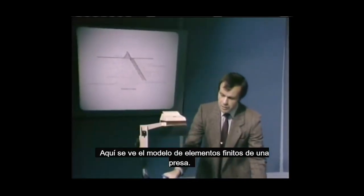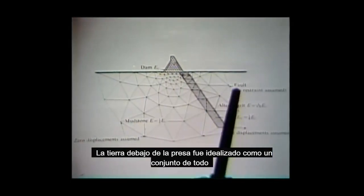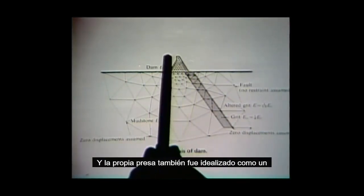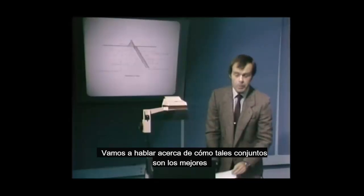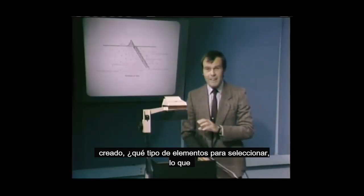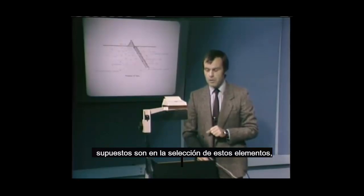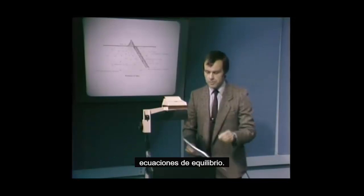Here you see the finite element model of a dam. The earth below the dam was idealized as an assemblage of such elements here, triangular elements now, and the dam itself was also idealized as an assemblage of elements. We will be talking about how such assemblages are best created, what kinds of elements to select, what assumptions are in the selection of these elements, and then how do we solve the resulting finite element equilibrium equations.